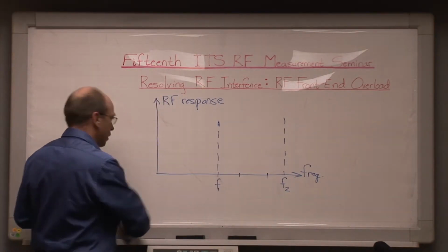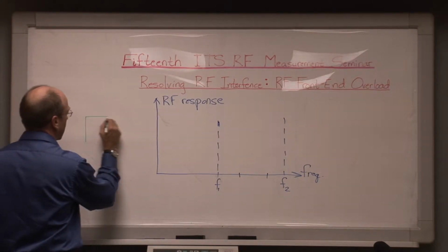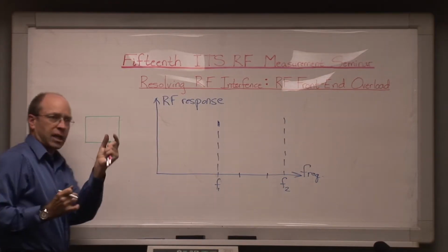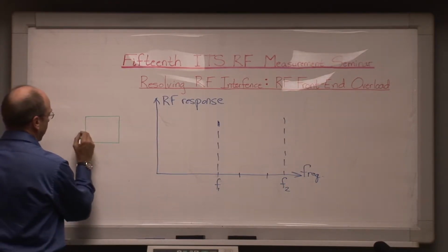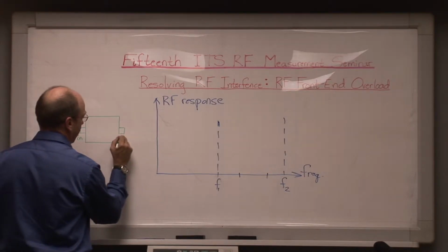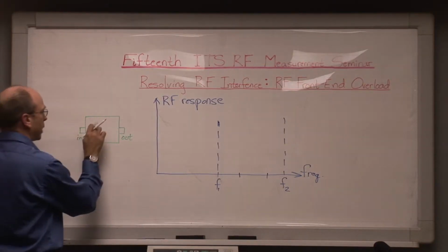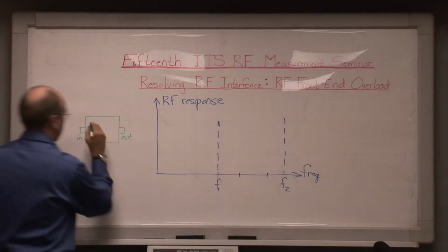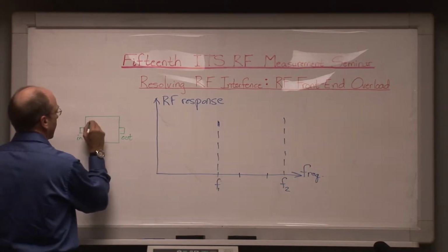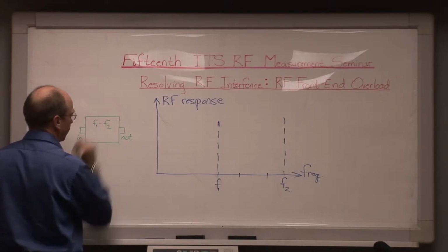And so they buy a low noise amplifier that's spec'd to work across that frequency range. And in fact, you'll get the low noise amplifier, it'll come in a package, greatly magnified here. This is probably only a couple inches across. And it'll have a spigot for input and a spigot for output. And right there on the package, it'll say, in some coded nomenclature usually, that it operates between F1 to F2.